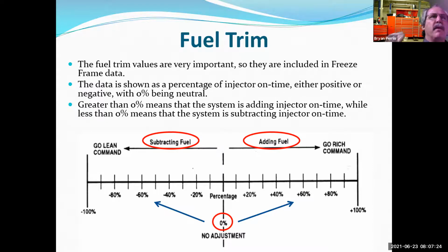For example, if I have a fuel system that's supposed to operate at 40 psi, but there's only 30 psi, the O2 sensors would indicate that we are having a lean condition. We would increase the amount of time that we're holding the injector open to get the oxygen sensor to say that we are back close to that stoichiometric ratio. But in reality, we haven't added any fuel. We're back to the same amount of fuel that we were supposed to have in our base calculations. It just took 10% longer injector on time in order to accomplish that, or 20% or whatever.